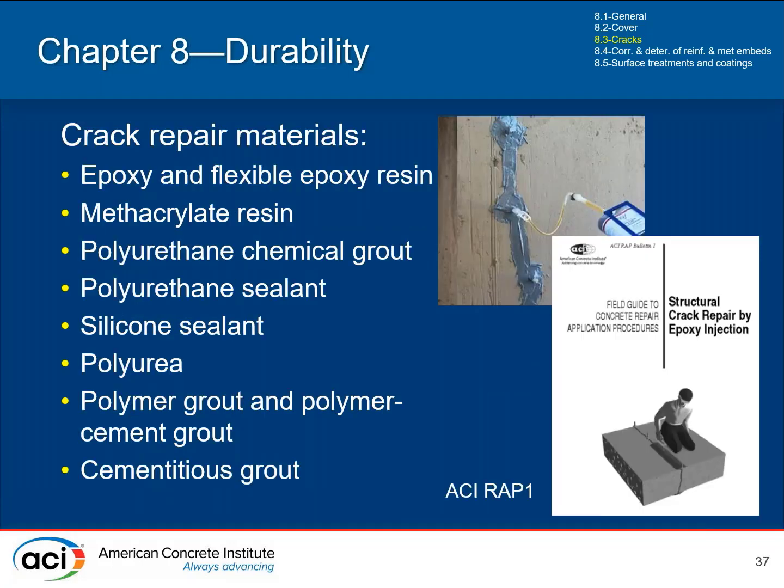Just wanted to touch again, while I'm talking about cracks, there are a lot of different repair materials and approaches. One of the most frequent is epoxy injection. And if you're not familiar with the ACI RAP documents, they're an excellent resource for information about repairs and repair approaches. It's in many ways written from the contractor viewpoint, but as an engineer, I find it invaluable, understanding what the limitations are, what the requirements of the repairs are. They're very short documents, they're very practical. If you're not familiar with them, definitely seek them out.